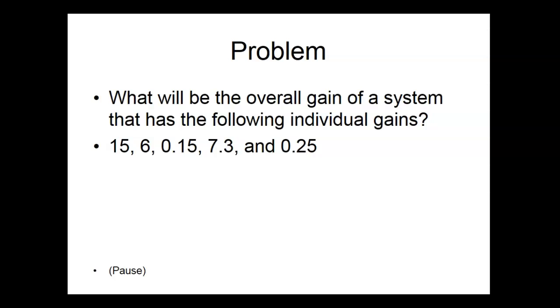So that's the advantage of a Darlington pair. A Darlington pair means, as we talked about, we take the emitter of one transistor and feed it directly into the base of another transistor. And right now I'm just going to put a resistor right here. So let's say this guy here has a beta of 30. This guy here has a beta of 30. What would be my total beta?